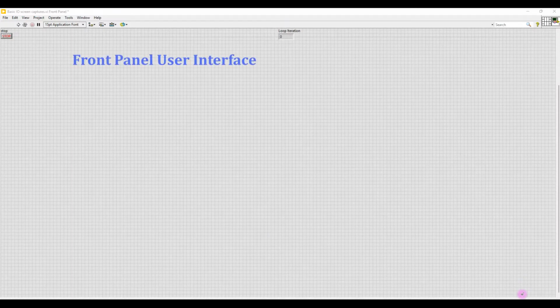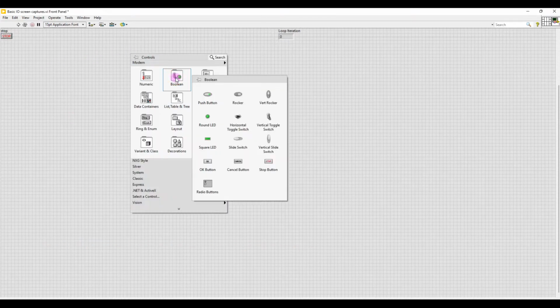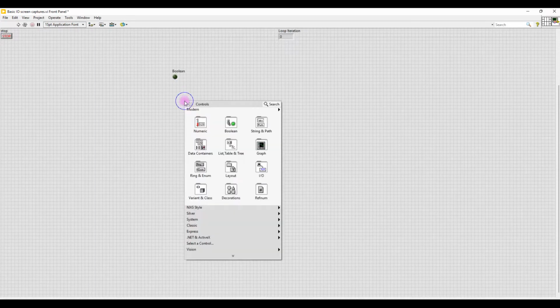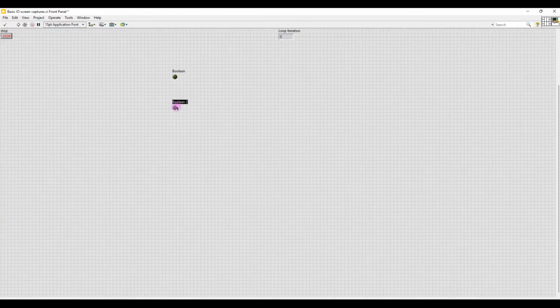Now let's create a digital input so that we can see what's happening in our logic inputs. I'm going to start off by placing 2 round LEDs on the screen. It could be square, just about anything you want. And I'm going to give them a name because I know this one is going to represent the start push button, which is on bit 5. I'm going to write that down too. Very useful to put which bit you're working with. And if you need to troubleshoot, you'll have that information. So I'll label this stop, and it's on bit 4.